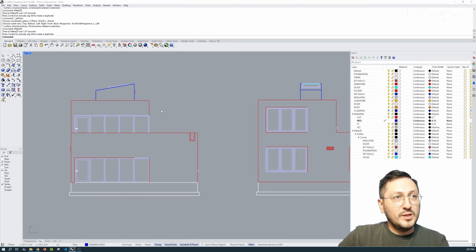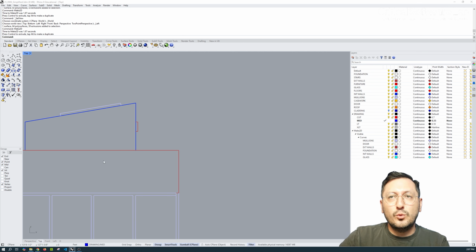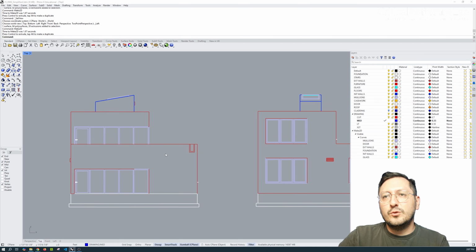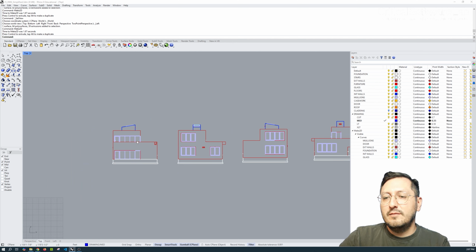We will need to manipulate the lines later on. Make2D gets you about 95% of the way there, but you will have to double check that all the lines are exactly where you want them for your drawing. So there's always some extra drawing or extra trimming or editing that you have to do to make2D drawings. That's always very important to keep in mind. Elevations are the easiest drawing that you can make in this way.